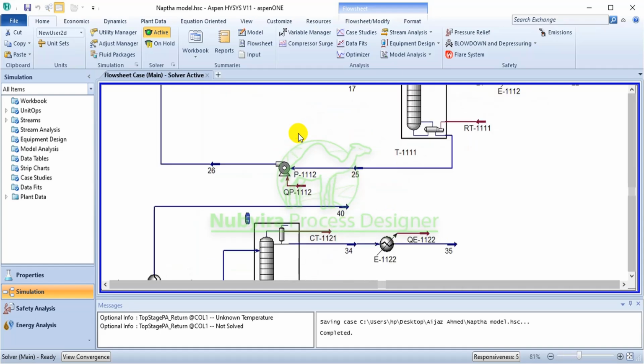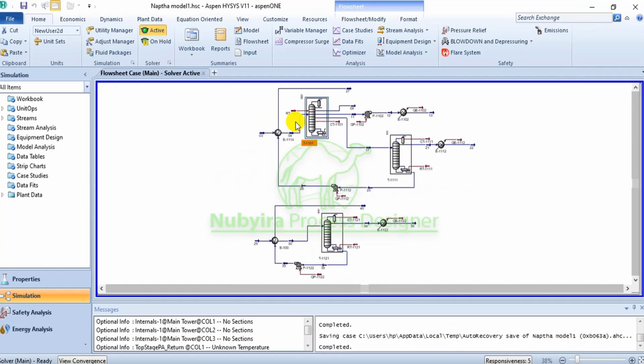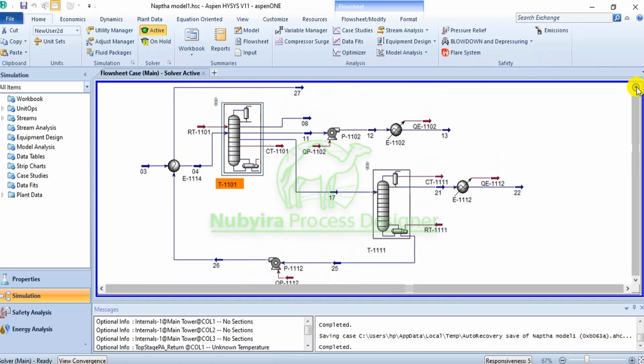Today we have a naphtha splitting unit for a refinery. We have three columns. This one is the naphtha pentanizer, this is the naphtha splitter, and the last one is the light cycle naphtha splitter, because this is another stream. This is the naphtha stream that is gotten from the crude distillation units. You are now concentrating the pentane content of the naphtha. That's the meaning of the pentanizer that you have in the first column.